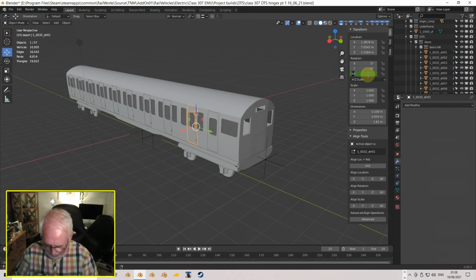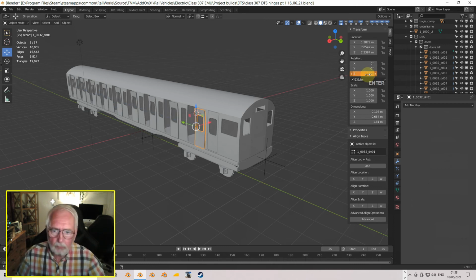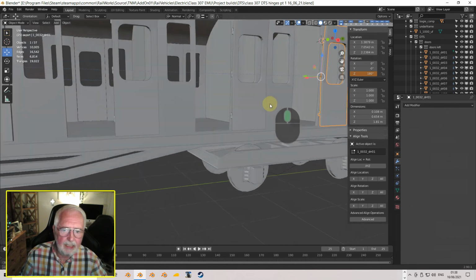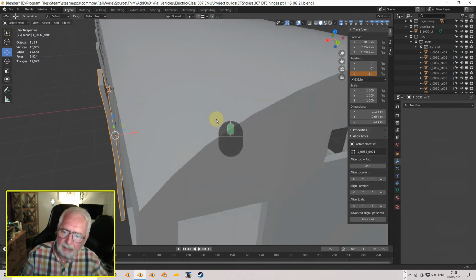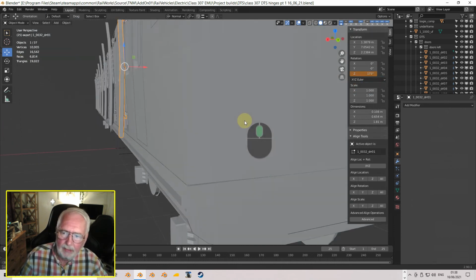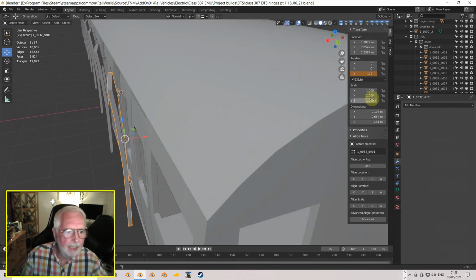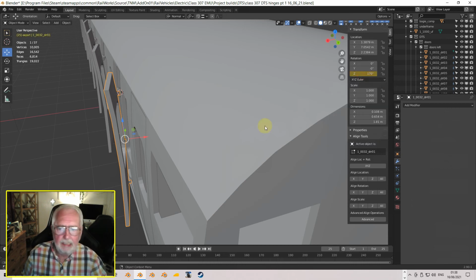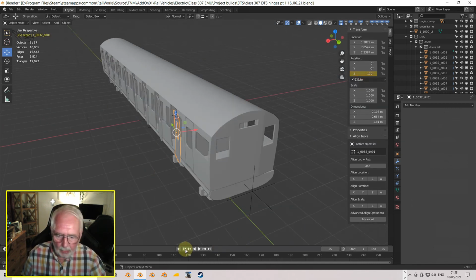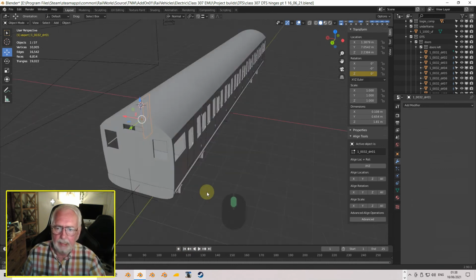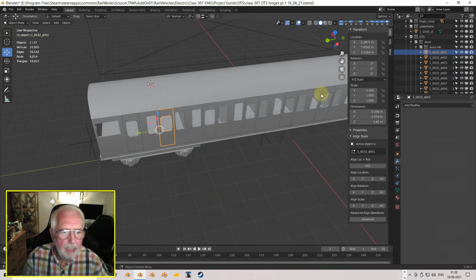Okay, and let's make this 180 degrees, so it's right open, really flat against the door. Probably not, because we're going to have a handle there. So let me take it back a bit. We've got to take account of the handle that's going to be there. So let's make that 170 degrees. There we go. Okay, and let's insert single keyframe. Go back to the start and just play. There we go, and the door is opening, and all the doors are opening. Same here, so let's make sure we're on 0.